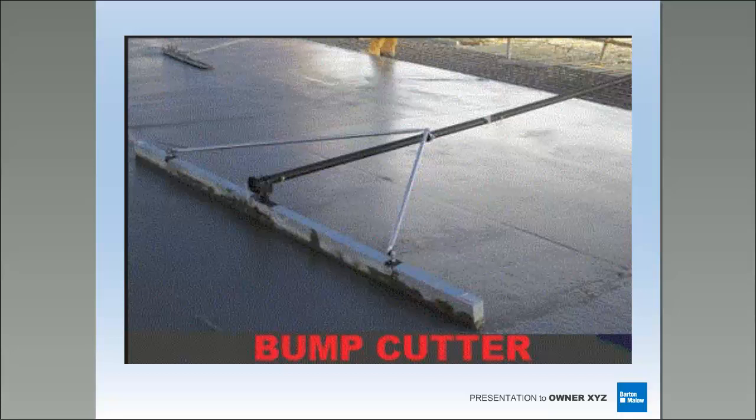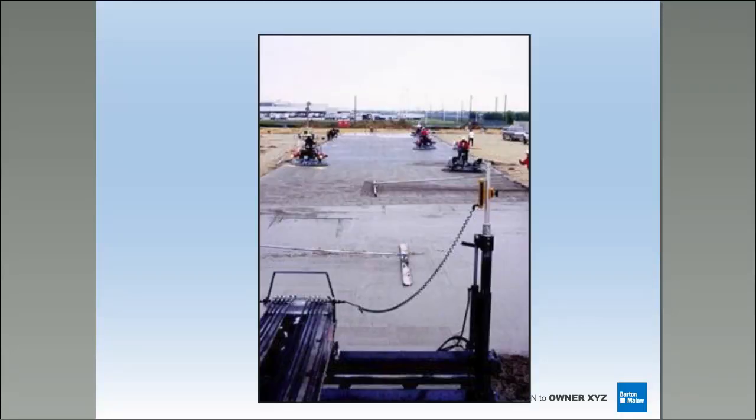And if they're going flatness of the floor, then they have to understand as a polisher, if I'm running a bump cutter to achieve my flatness, there's only so much I can do as a polisher because I'm dispersing that cream, and you're not going to have an even surface to be polishing the cream layer. All right, it'll be flat as heck, but you will not have that even undersurface, right? You may make a pass and hit stone on one part and all cream on the other. So be cautious of that, all right?